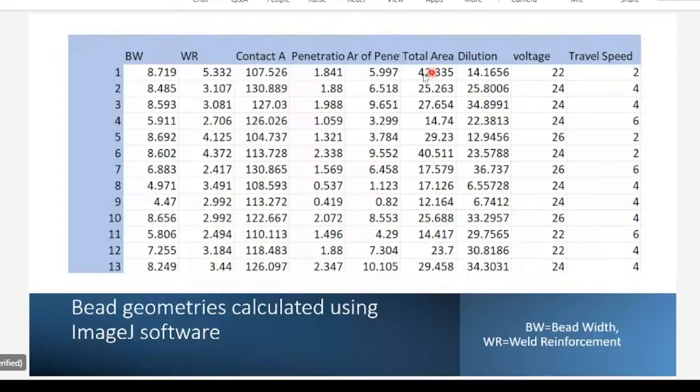What is our ultimate goal? To find the best parameter which can generate the best weld bead aesthetics. After getting the optimal weld bead within the range of this design of experiments, if we can get the optimum level of the process parameters and an optimum output, then with that optimum process parameter we can fabricate a WAAM component.